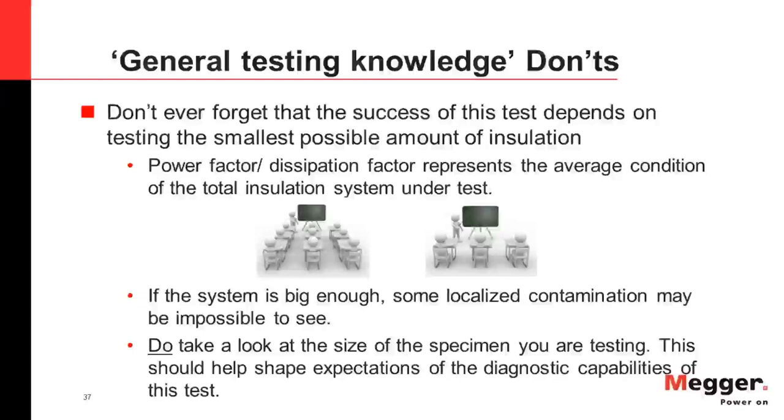So with power factor, if the insulation system is big enough, some localized contamination may be impossible to see. So do take a look at the size of the specimen that you're about to test, because this will help shape expectations of the diagnostic capabilities of this test. A good example is a large single-phase autotransformer with an inaccessible tertiary.